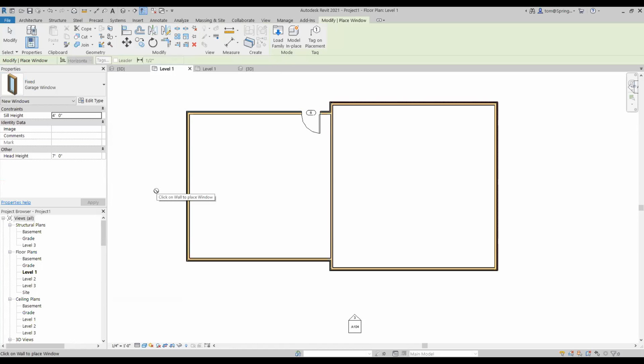Now here's an interesting thing about Revit. When I pull this right here, you're going to notice that as soon as I touch the wall close to the midpoint, it says, oh, Tom wants to put this right in the center. So what it's doing there is automatically doing it. You're going to notice that it's 11 foot 5.5 on each side. Revit's going to try and do that for you. Now, of course, you don't have to use that, but in this case, I do want it centered. So I'll just go ahead and drop it right there.